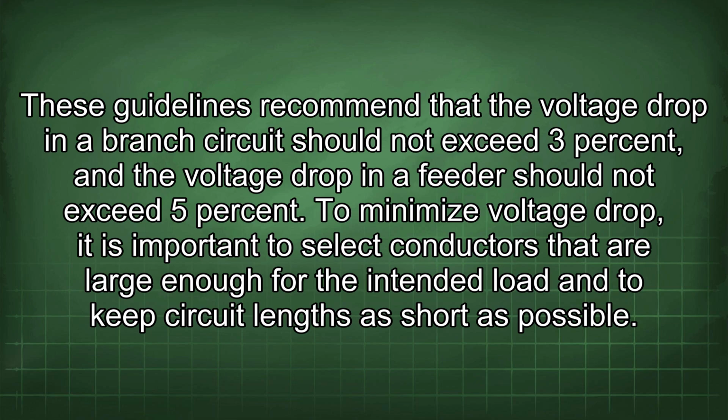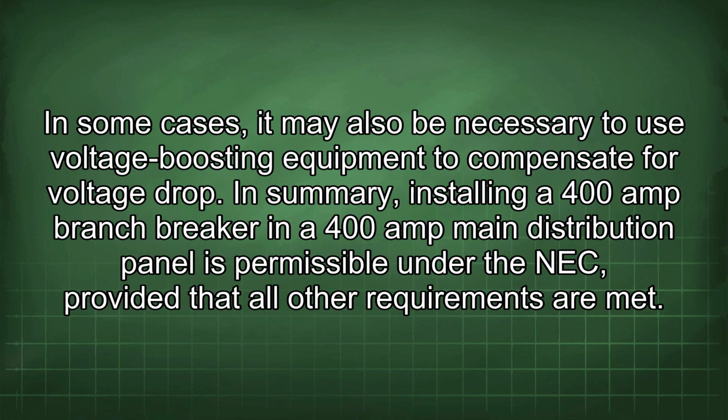To minimize voltage drop, it is important to select conductors that are large enough for the intended load and to keep circuit lengths as short as possible. In some cases, it may also be necessary to use voltage boosting equipment to compensate for voltage drop.